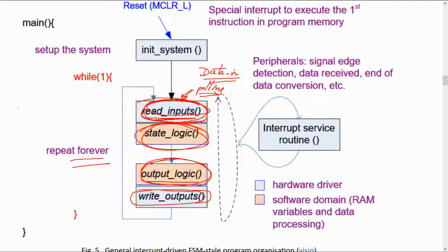And you know, because from time to time someone clicks a button, you have to detect that edge, and this will happen, for example, when the system is running. The system is interrupted because at this time this event happened, and this is when you will go and execute the interrupt service routine, specifically for two important ideas: setting the clock flag, and clearing the external interrupt flag, the hardware flag.